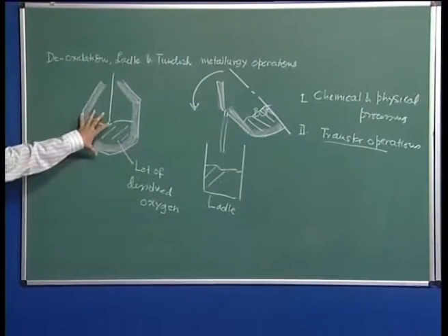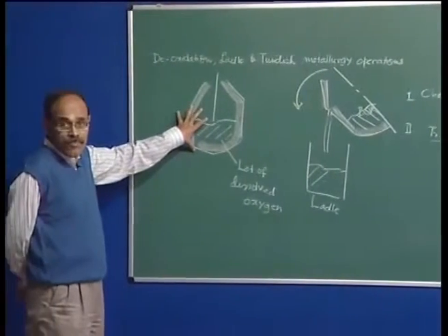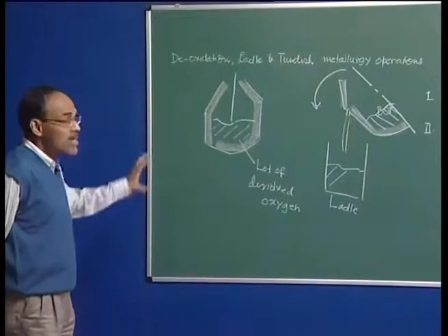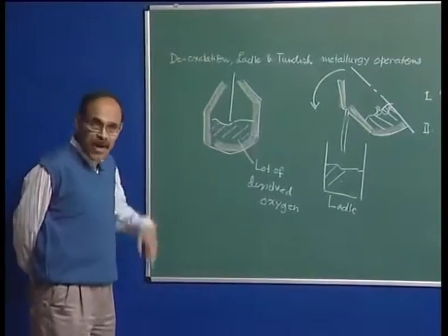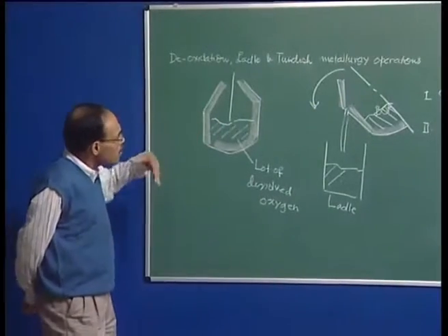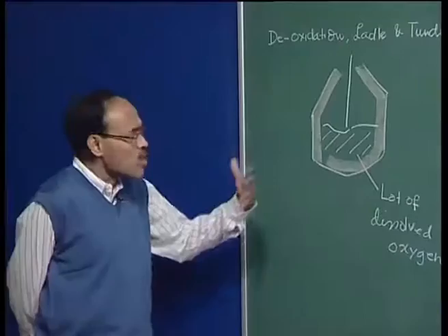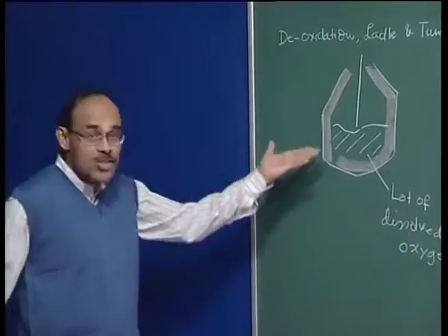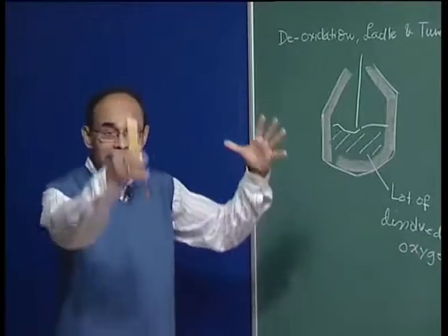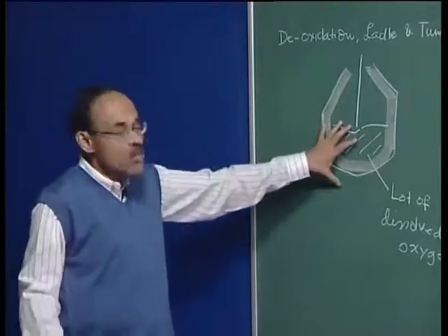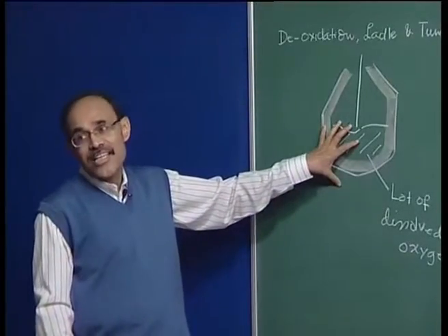So the objective of primary steel making, as we have seen during earlier lectures, is to primarily decarburize the bath, because if we wish to take out many other aspects of steel making, for example, composition adjustments, temperature adjustments, then unnecessarily the duration of the blow is going to be substantially large.